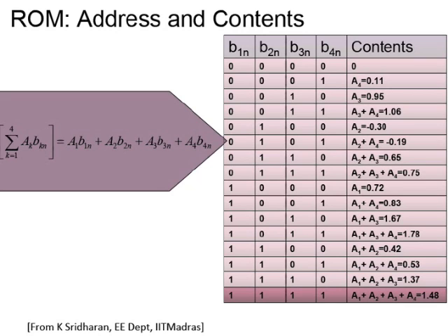But no, see, when we discuss memories, we will discuss refreshing and so on. You can lose memory, but for static random access memories, you don't have to do refresh. The information is always stored. But it might leak. When I say leak, it doesn't mean the information gets leaked out. There is current leakage and you have power.